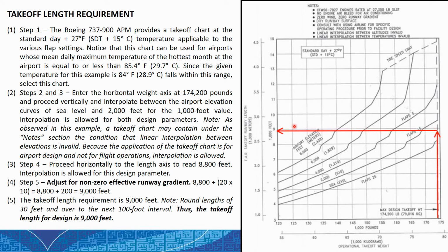So this is the length axis, and this is the operational takeoff weight. Here, around here, we get this point, and it is between 8,000 and 9,000 feet.